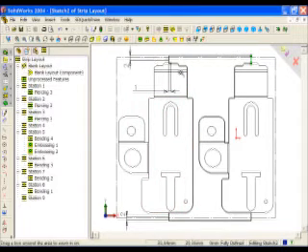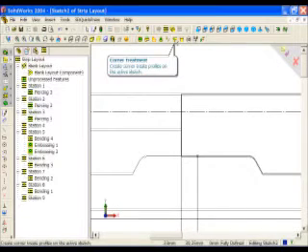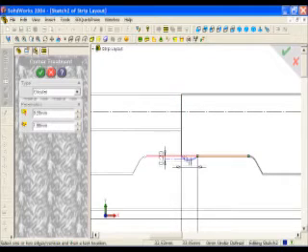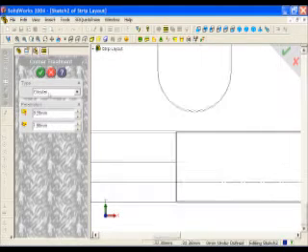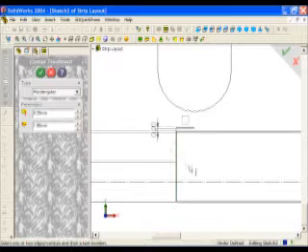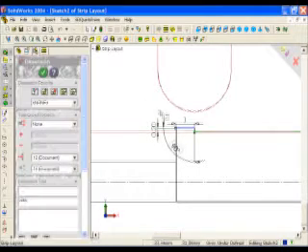Let's zoom up on a corner here and talk about some of the other enhancement tools. One's called corner treatment. Corner treatment allows us to simply pick a line and it automatically puts in that arc and the trimming process with the dimensions all at once. Let's do that one more time, down below here. Just do a rectangular one and we'll use the same sizes. Click on that edge, and it automatically extends, trims, whatever it has to do, making that sketching process very easy.